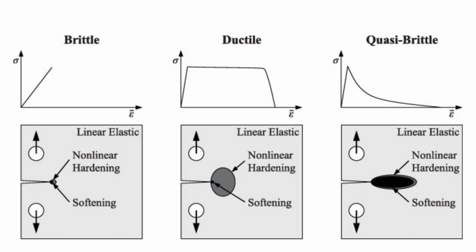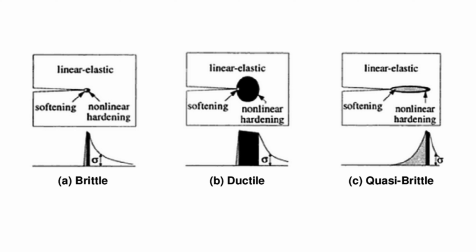Initiation and propagation are considered to be controlled by the extent of total plastic shear deformation. Crack initiation and crack propagation occur when deformation exceeds a critical threshold value, which can be equated to threshold conditions determined from linear elastic fracture mechanics analyses. The appearance of micro and macro cracks is largely correlated to the microstructure and heterogeneities of the material, the mechanical stress, or even the effects of the environment.